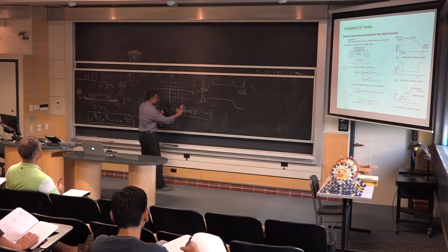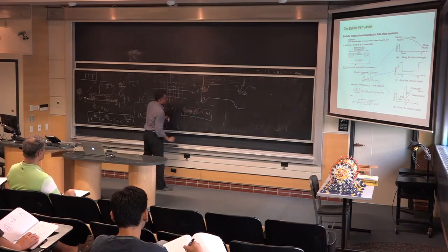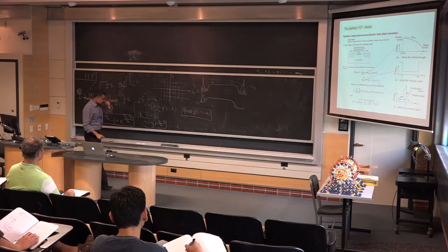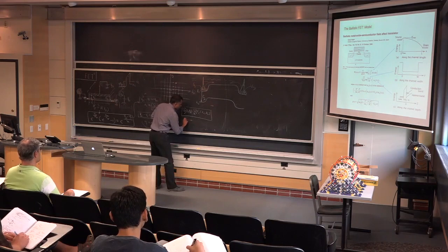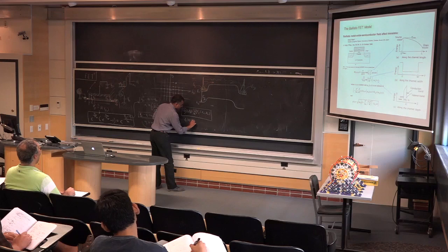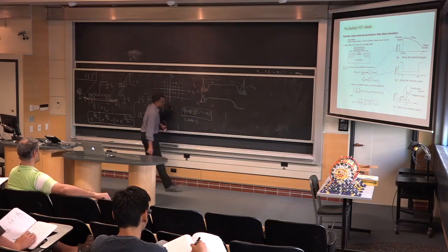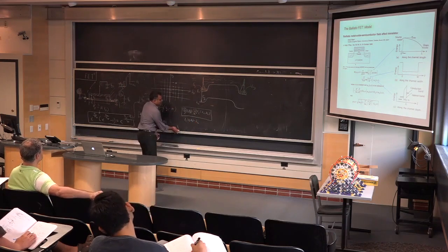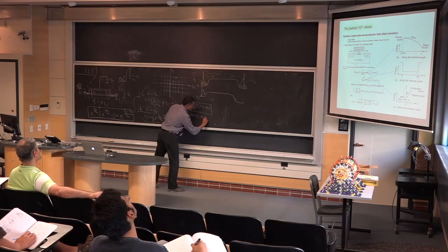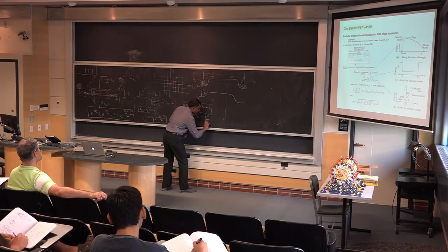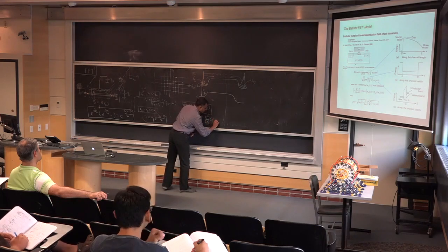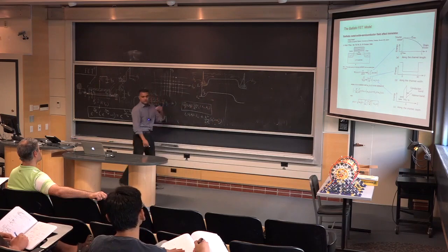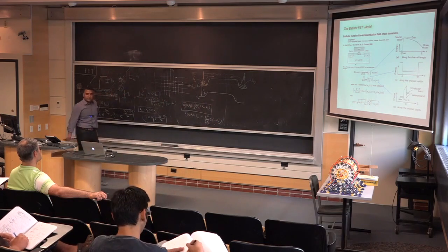But for our discussion, this is all we need for now. This looks complicated, but really what we're going to do is assume that we are dealing with parabolic band gap semiconductors, meaning that the conduction band structure is the band edge plus h bar squared over 2 m star of the conduction band times kx squared plus ky squared. So we're saying it's a parabolic band structure.